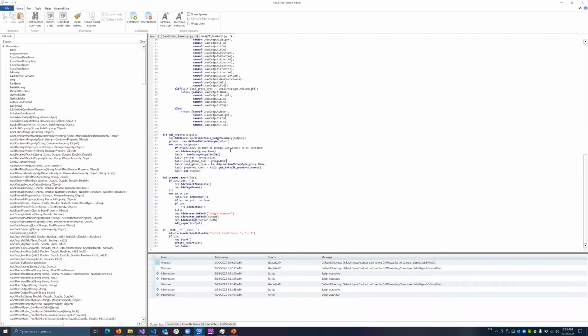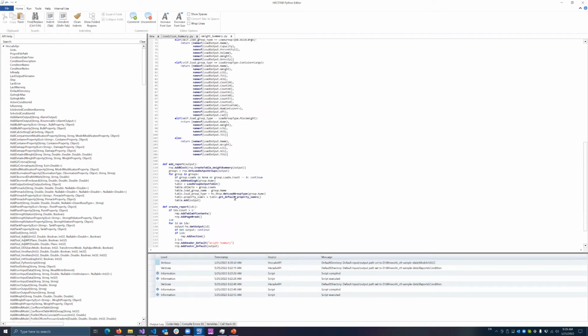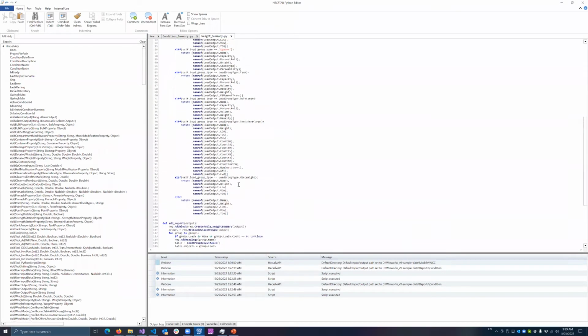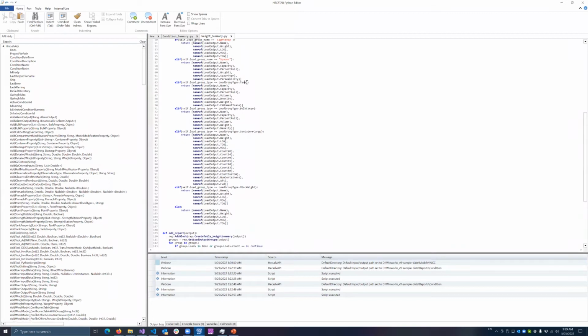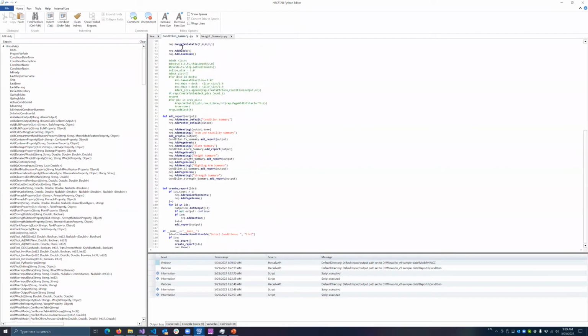And if we want to add different columns to that table, one way we can do it is to just edit the default ones, or what we say are the default ones within that group. So I'll go up here and say, I want it just for the tanks. I can change this list here. I'll copy this and say, I want to add the LCG, TCG, and VCG. So I'll save that and come back to my condition summary.